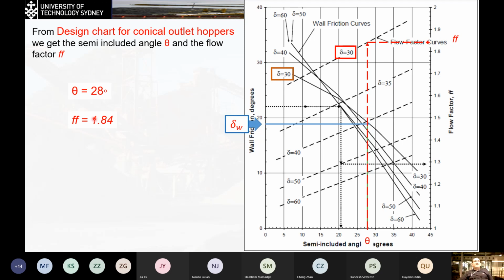So I had the FF. The slope of the line I'm going to be sketching is going to be equal to 1 over FF. The other parameter, the MFF, is going to use the data we got from the table, which is the sigma 1 and the sigma c, to sketch the curve.